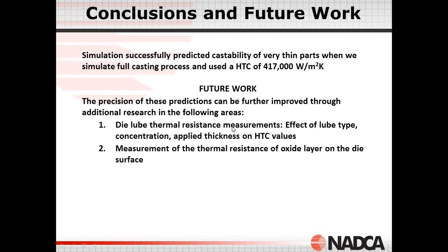The precision of these predictions can further be improved through additional research like measuring the thermal resistance of the die lube for every casting condition, because it turns out that the thermal resistance of die lube varies significantly based on die lube type as well as concentration.